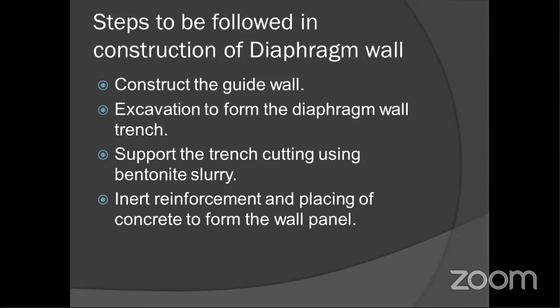excavation, we cannot do the excavation instantly, because we have to do bentonite circulation permanently, so that we can resist the soil collapse inside the trench. And also after that, reinforcement fabrication, placing and concreting will be taking place.